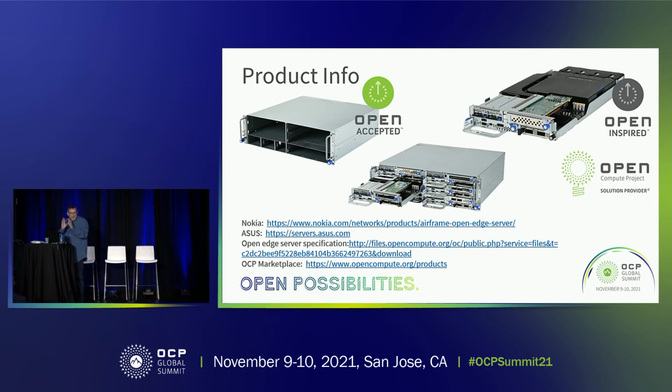And that's a standardized interface on the OpenEdge. All sleds have that in common. The signals actually go down to what would be in the middle, or the right hand most of the 3 pieces on the left, which is the rack management controller. In addition, it has a BMC built on that provides telemetry information and control of the power supplies, but it also has an Ethernet chip built into it so that it can provide over that signal connector the 1 gigabit Ethernet to each of the sleds.